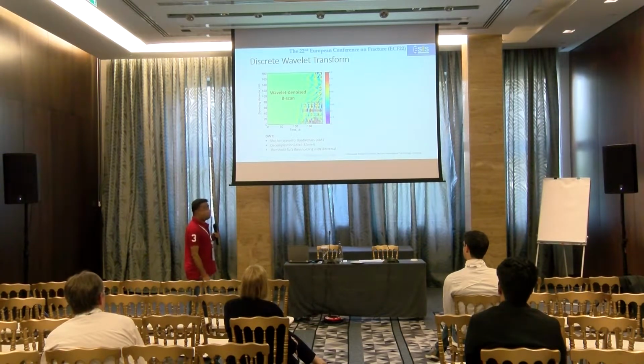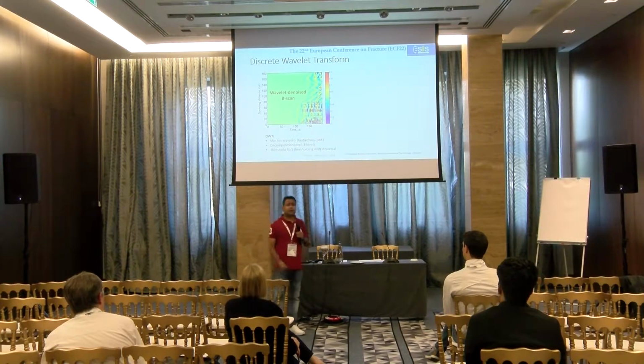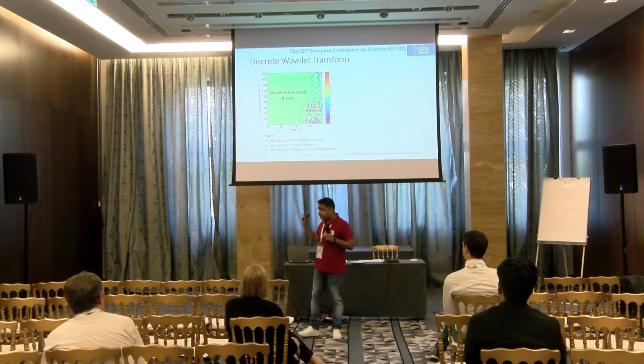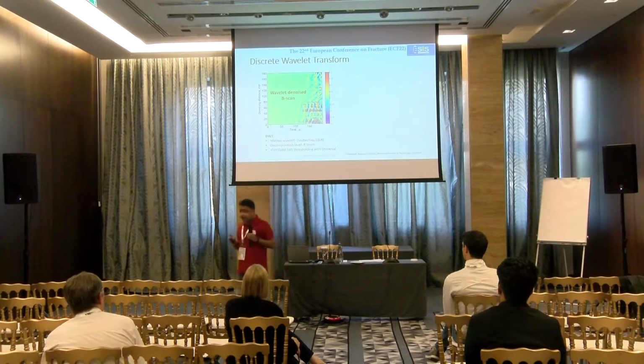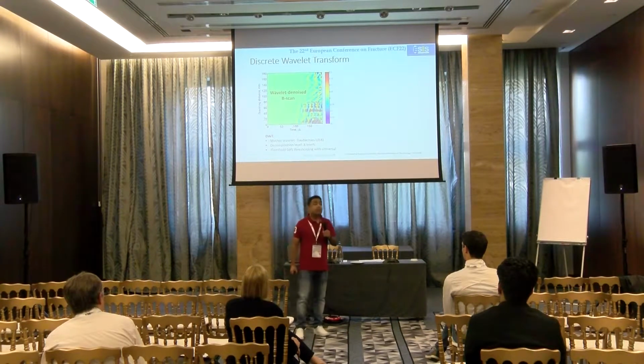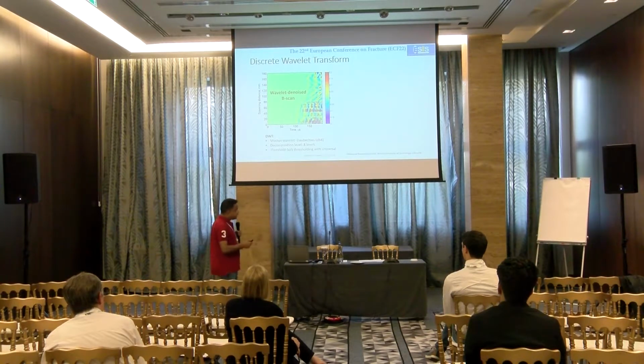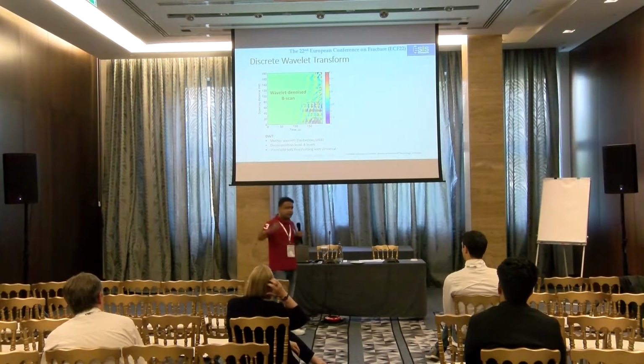So this is the denoised B scan after applying the discrete wavelet transform. We used here the Daubechies mother wavelet. There are many wavelet families such as Daubechies, Haar wavelet, Symlet wavelet. But we selected the Daubechies wavelet because we did not observe any significant difference while using the other wavelets, and as the Daubechies wavelet is orthogonal in nature and more energy preserving, that is why we selected it. And why DB8? There are many orders of Daubechies wavelet, DB2, 4, 8, 16, in the order of 2.